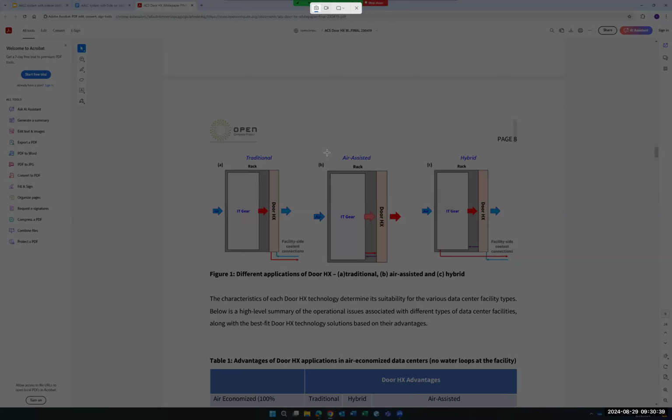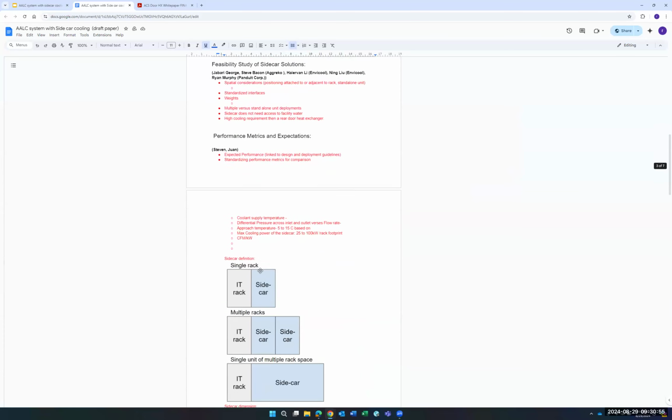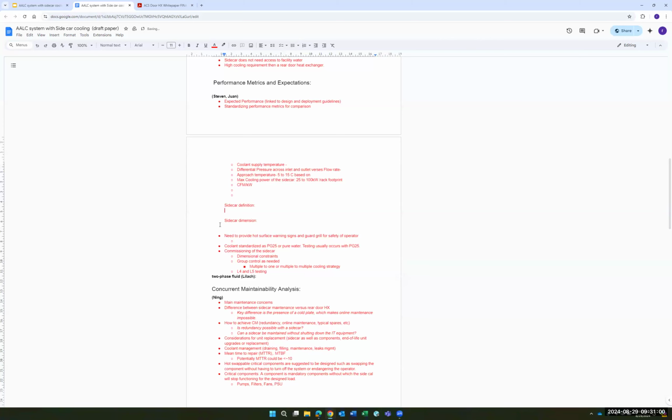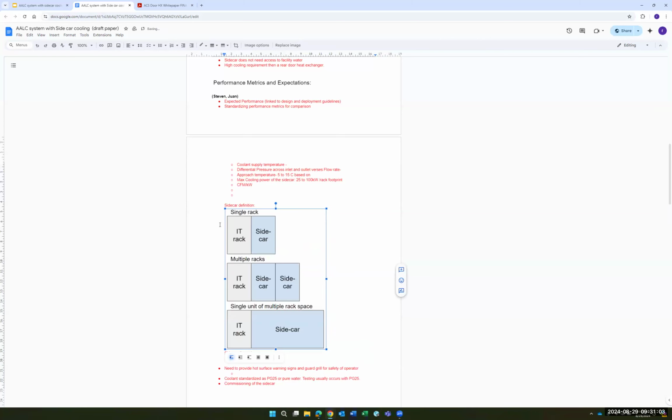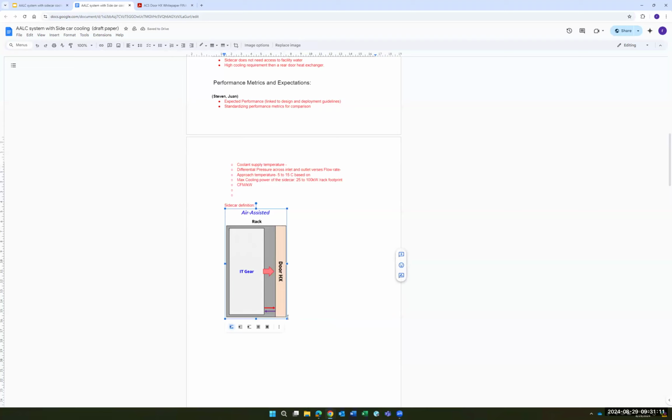I need more than that because I'm filling it full of NVIDIA GPUs, so the only alternative for me is to go to a sidecar. I see. And if they say that they've got 125 kilowatts of cooling requirement, then they can see what the upper bound is for a single wide sidecar, and they can say, okay, I can't get there with a single wide, but I could get there with more than a single wide sidecar, either multiple sidecars or a wider sidecar.